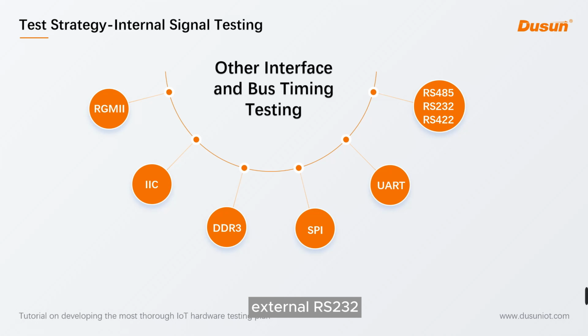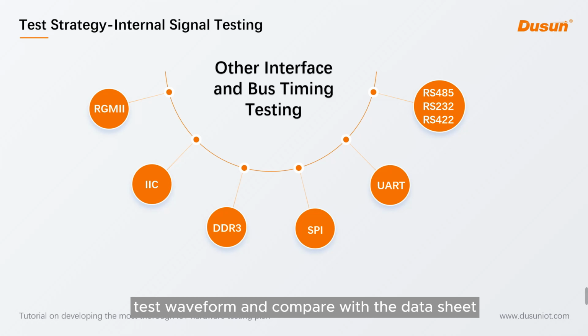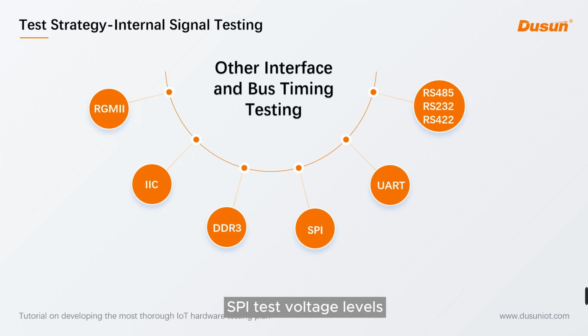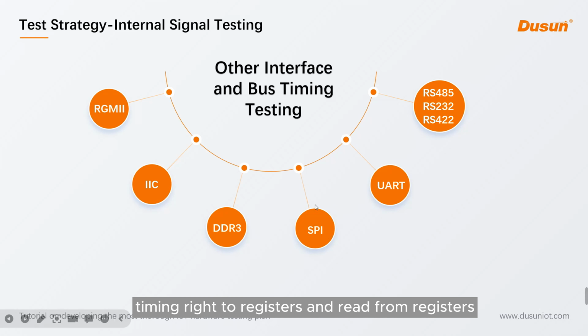Loop external RS232 hardwire into internal program. Run UART test program, test waveform, and compare with the datasheet. SPI, test voltage levels, timing write to registers and read from registers.